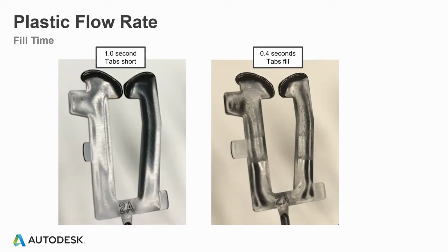But the cosmetics on the part look rather nice. At 0.4 seconds, those tabs do fill. Moldflow was pretty dead on with those time ranges of where the tabs short versus where they don't. But now at 0.4 seconds, you can see there's some cosmetic issues in this part.